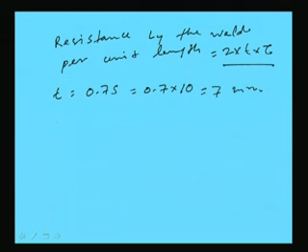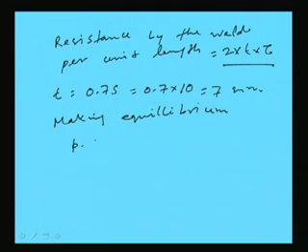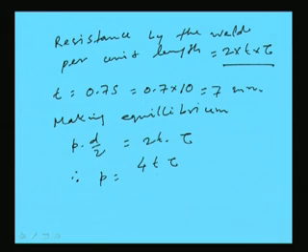So, making equilibrium means the internal force will be equal to the force resisted. So, making equilibrium we can say P into D by 2 is equal to 2 T into tau. So, P will become 4 T tau by D.